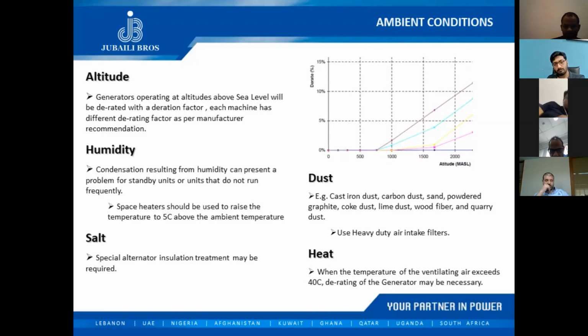Less oxygen, Abdul Karim. You're right, less oxygen. With altitude, air density decreases. Wally also answered with the same. With altitude, air density decreases, meaning there's less oxygen or less air going into the cylinders, into our burning chambers, which will result in lower power of explosion, so a lower output power of our engine. So this is related to altitude.